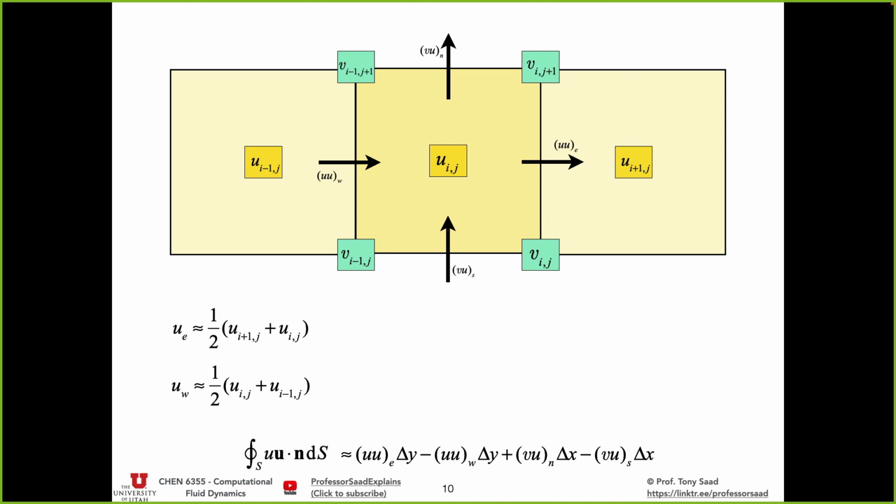So where do you have u velocities? You have a u velocity above it, right? But we're trying to express it in terms of those. You don't know these either, right? So what is u north? You have to grab uij and uij plus 1, the one above it, until you hit the boundary. At the boundary you'll have a specification, but in the middle of the control volume you have variables placed at those u control volumes. So we have to bring in the one above it. So now we have uij plus uij plus 1, the one above it, over 2.